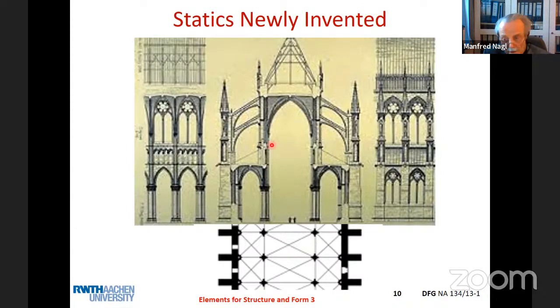We unfortunately lived through World War I and II. Some Gothic churches have been destroyed, but they are much less destroyed than the surroundings. If you look at the pictures of, for example, Rouen or Freiburg or Cologne and so on, you see there is no building standing in the environment, but the churches are damaged and still stand up. That is due to the fact that this construction of connected columns guarantees some flexibility against big blows.